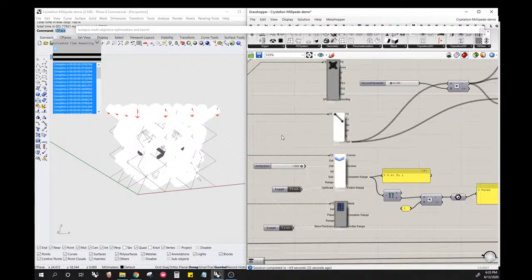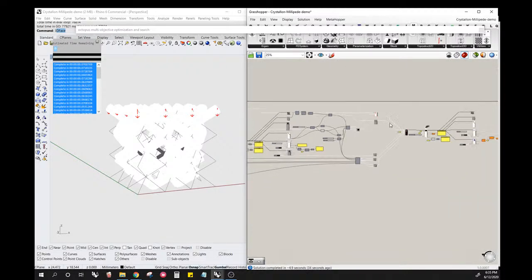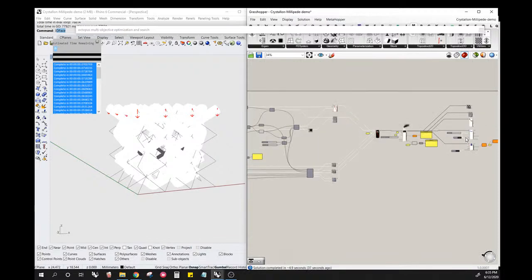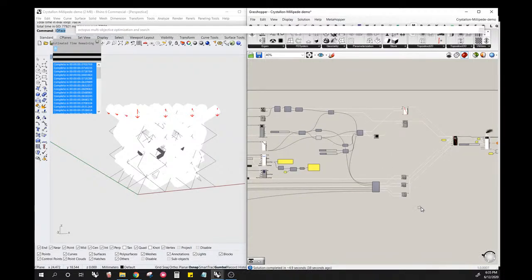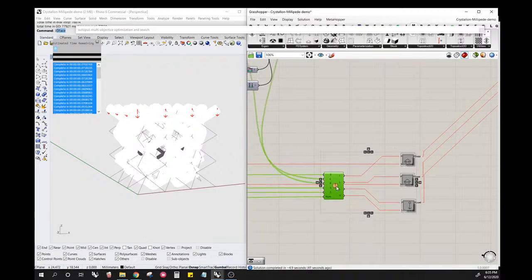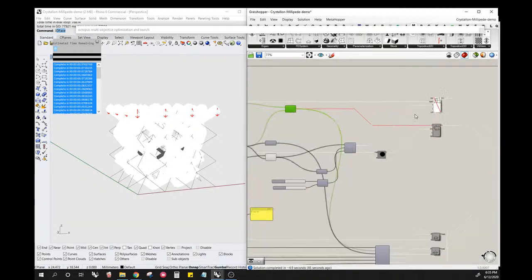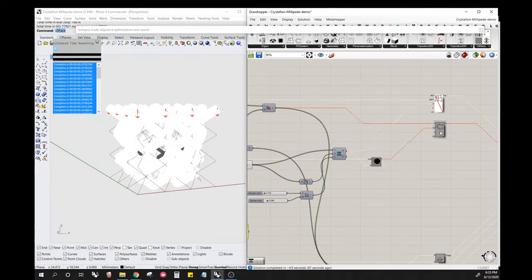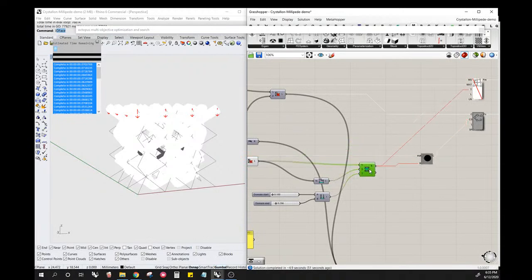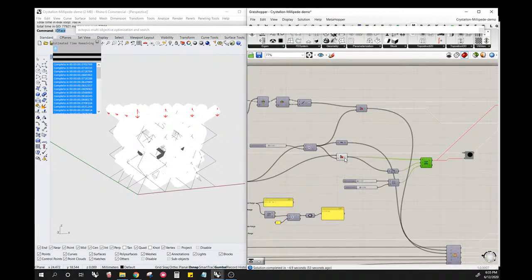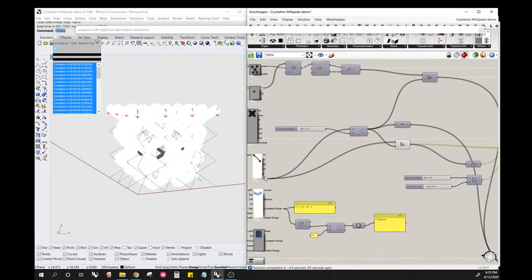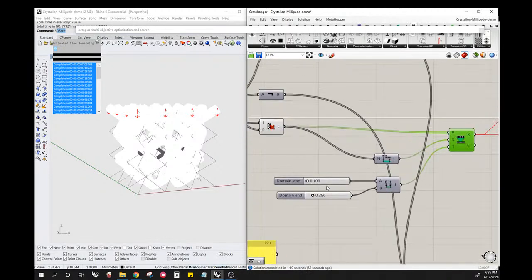And so what I typically do is I run a whole other simulation with the same boundary conditions, the same load, the same supports, but I make new beam elements here, and with the same material, but I change the radius, and what I do for the radius is just remap these values, these numbers from 0 to 1, to a new range of numbers.